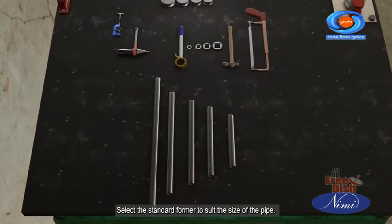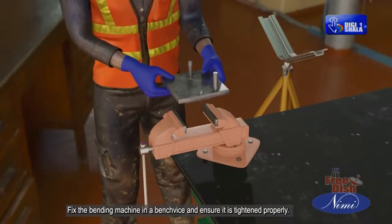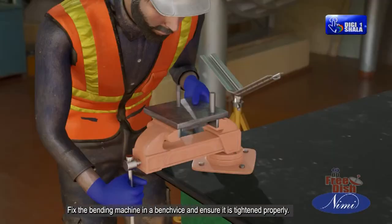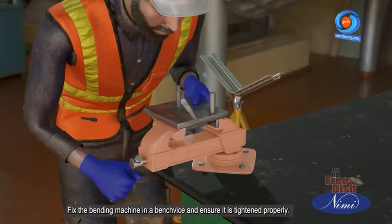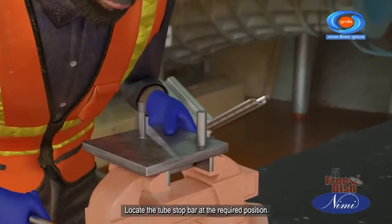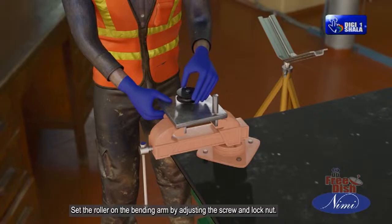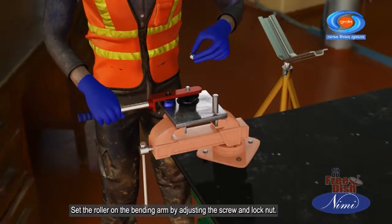Select the standard former to suit the size of the pipe. Fix the bending machine in a bench vise and ensure it is tightened properly. Locate the tube stop bar at the required position. Set the roller on the bending arm by adjusting the screw and lock nut.